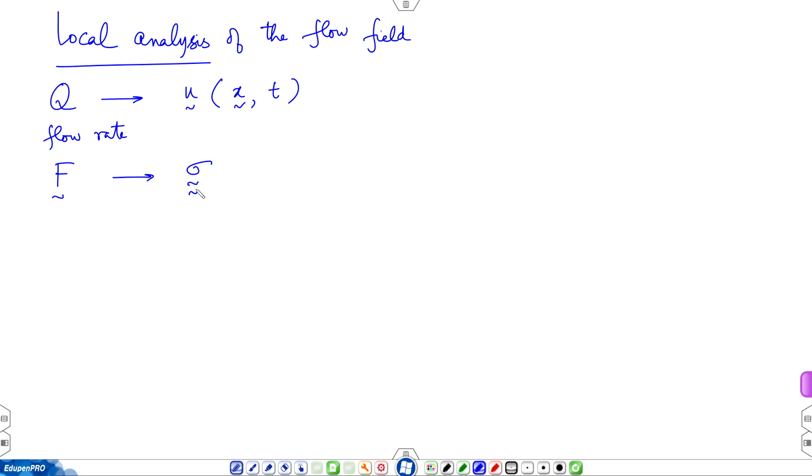Newtonian fluid is one for which viscosity does not depend on, we said, strain rate, which is just the velocity appearing in the flow field. Okay, constant. So, when you prescribe viscosity mu equal to something, you are really insisting on the medium being Newtonian. So, please keep referring to the initial discussions of this course.